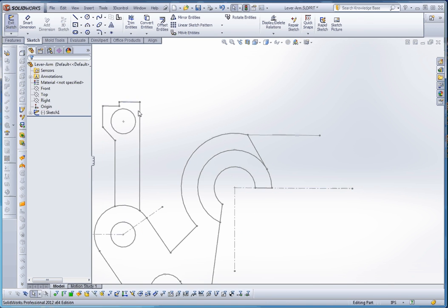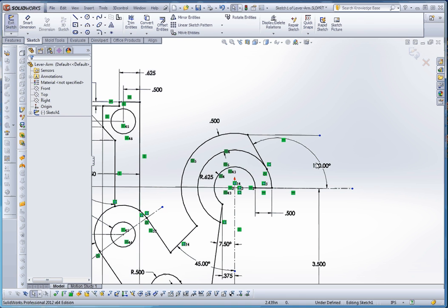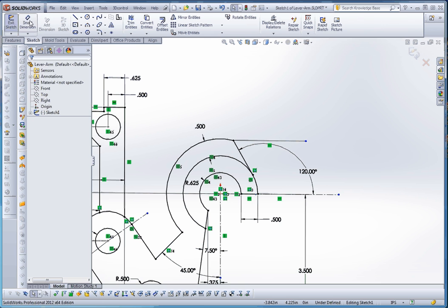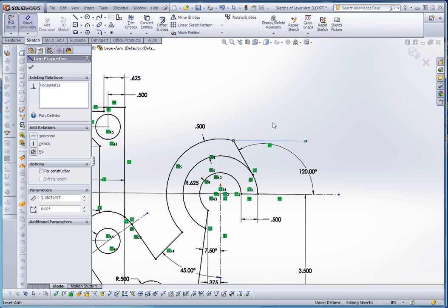If we went ahead and rebuilt this, you'll notice that sketch now is underdefined. Right-click on that sketch. Let's go ahead and redefine that. If we put a dimension on that line, it'll redefine itself. And you notice that that line turned orange initially because we pre-selected it. We put our mouse over it, but we didn't click on it. And right now, because it is selected, that line is yet a fourth different color, and that color is a light blue line. Actually, a fifth different color.